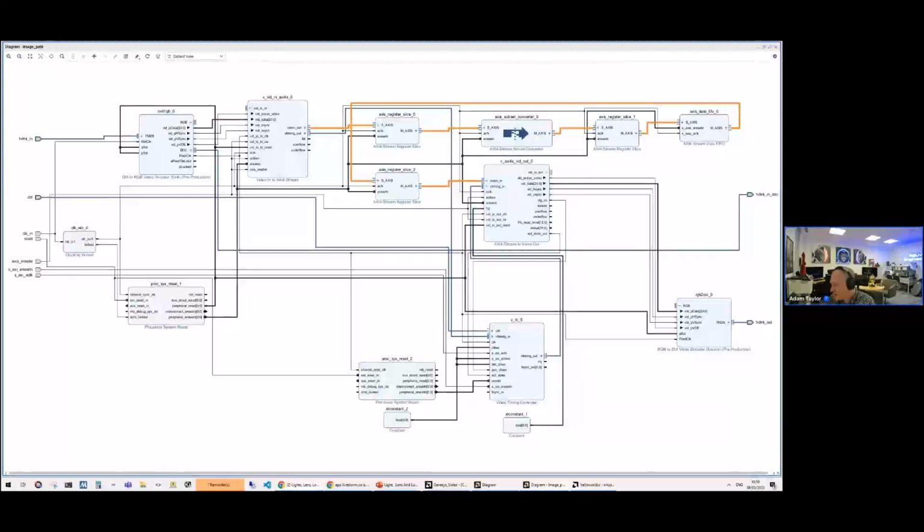Bobus, considering battery-powered devices and power consumption, with a camera image processed on an FPGA. In terms of power consumption versus performance, you can actually get very good performance from the FPGA. If you architect it right, you will also get exceptionally good power as well. But it depends upon what your constraints are.